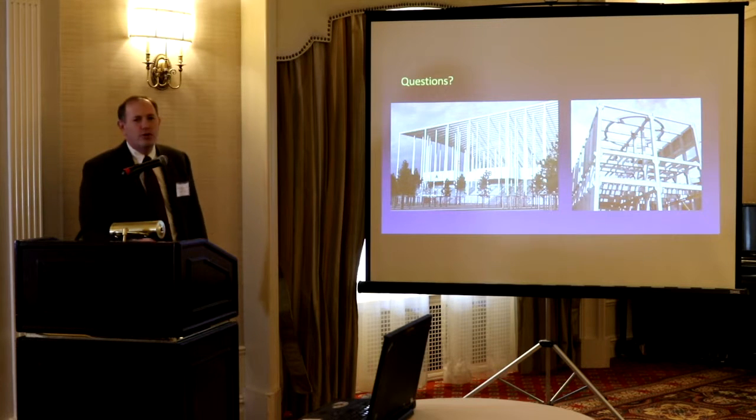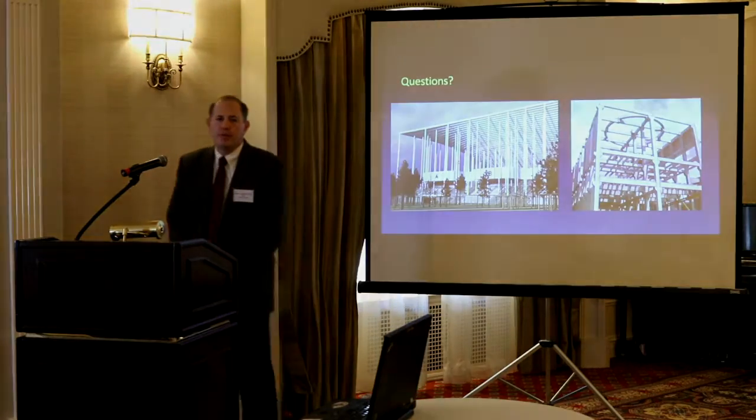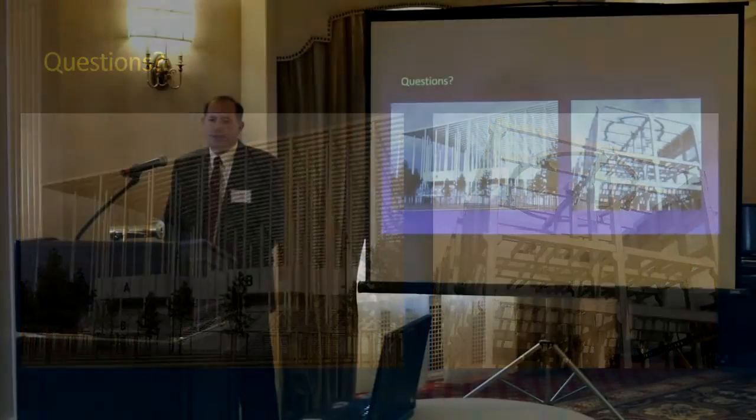So you can see they're using slender columns in the precast pre-stressed world quite a bit too. For PCI, we've also given some guidance to them. The 0.4 EI works really well too, so you can use the 0.4 EIs. We have the equations also, and those will work for the precast.